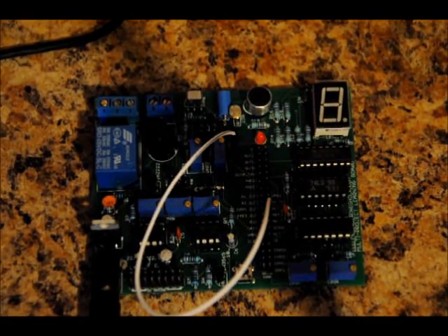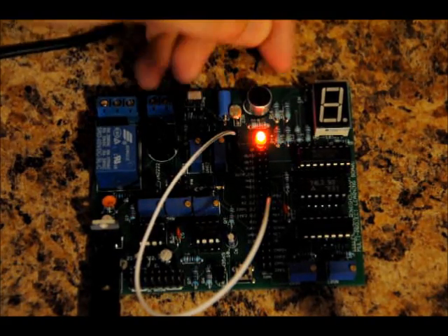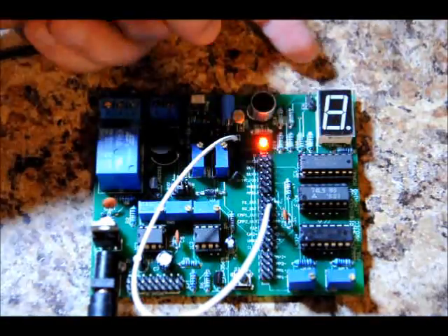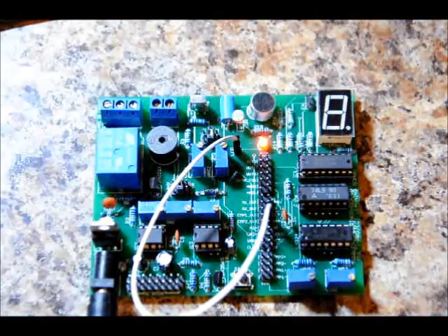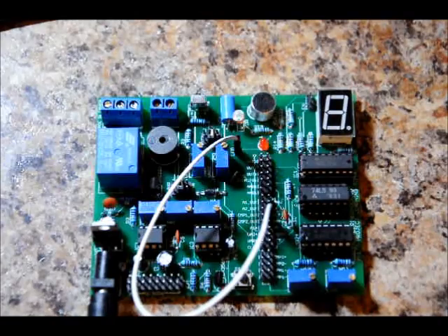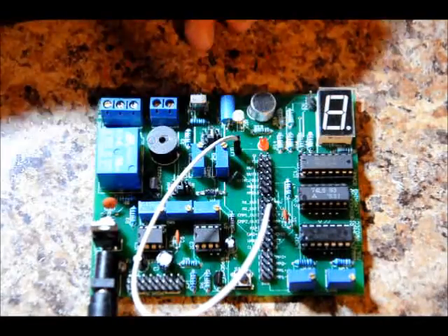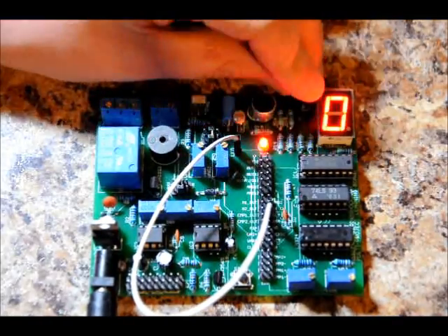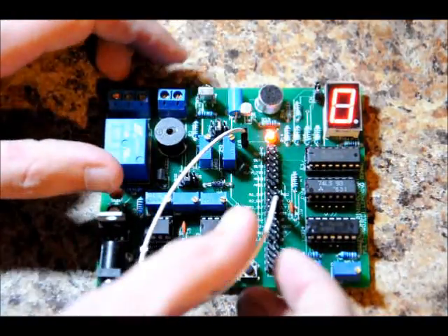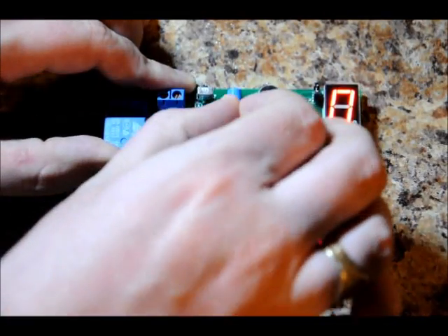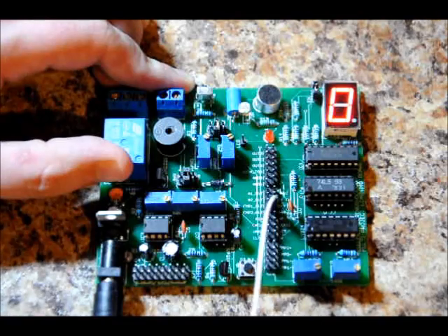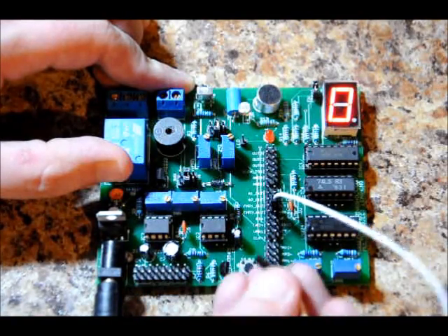Not a big deal. Now, there is a little 2-pin header right here that's labeled EN. Your learning board will come with a few 2-pin header jumpers, and this will power the 7-segment display. Now, as we talked about in the video, we're going to take this off the LED, the Astable output, AST output, and put that in the clock plus pin.